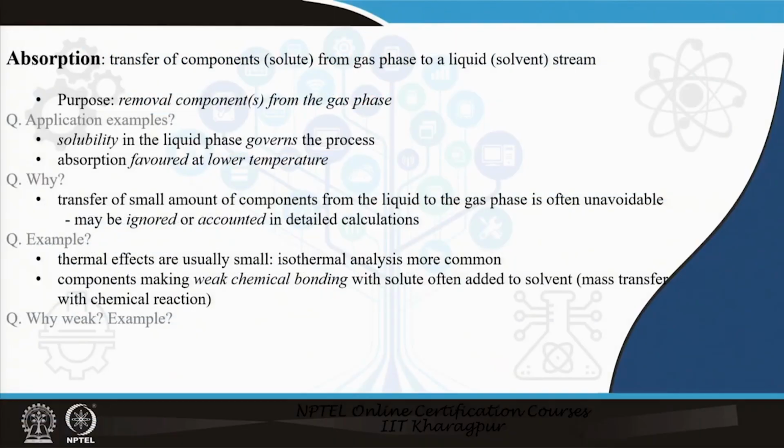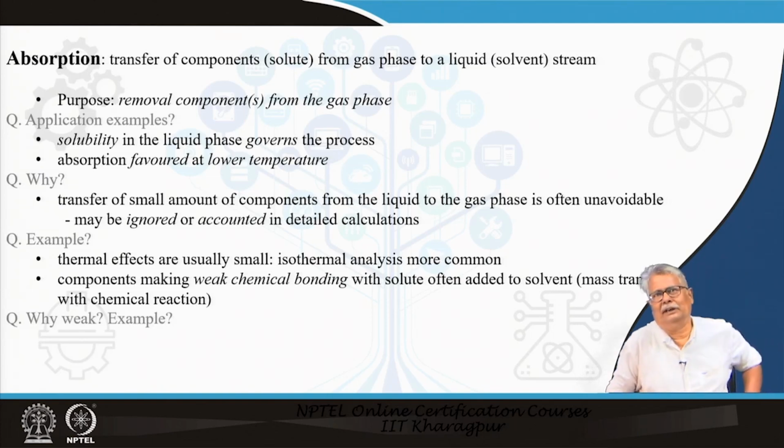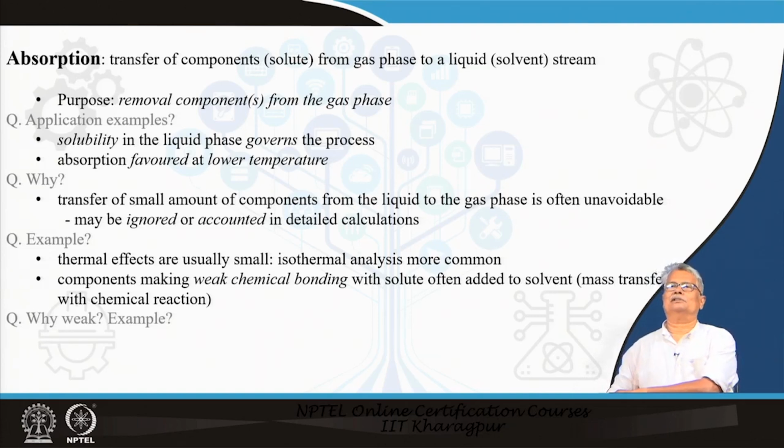To start with, let us look at the process of absorption itself. Absorption basically means a process in which some components which are present in the gas phase are getting transferred to a liquid phase which is brought in contact with the gas phase, the liquid phase being called typically the solvent, and the transferred component is called the solute, because it is quite more soluble as compared to the other components which are present in the gas phase. So, it is the case of a solvent and a solute, and the solute gets transferred from the gas to the liquid phase.